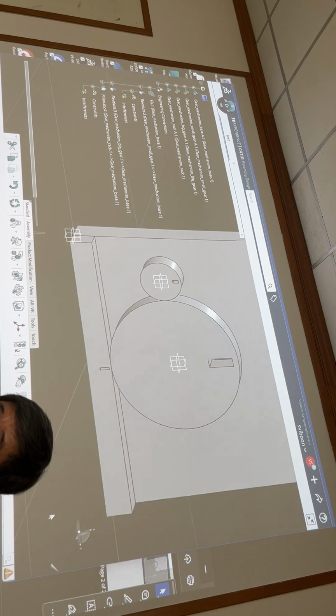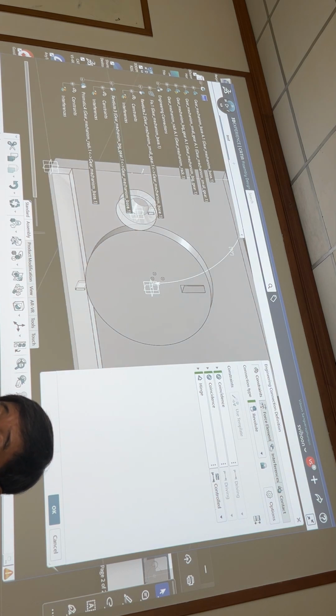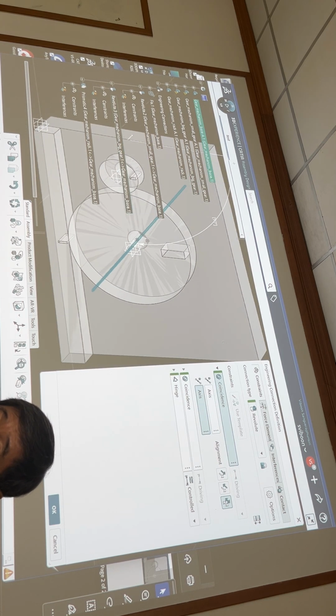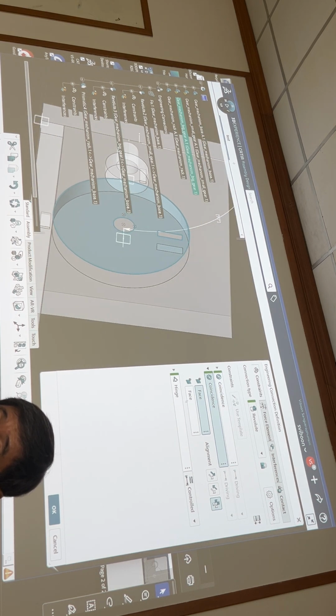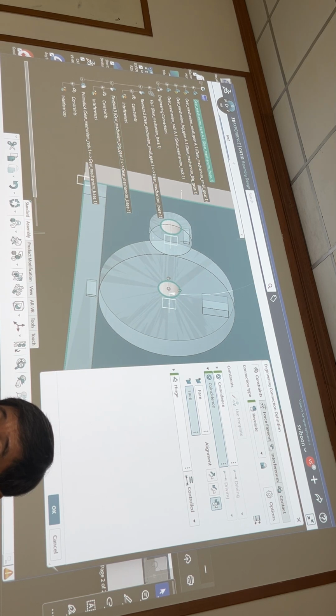For this one as well, you need revolute joint number 3. This one, you have between this big gear and the base. You see, you have an axis here, the axis of the fixed place, right? And the face between this face and the other on this face as well. Hinge, look at this one.